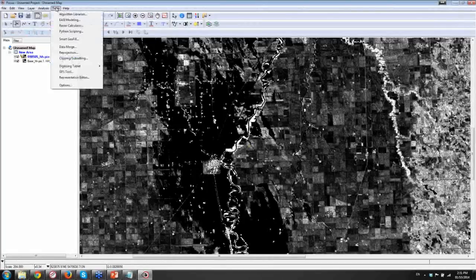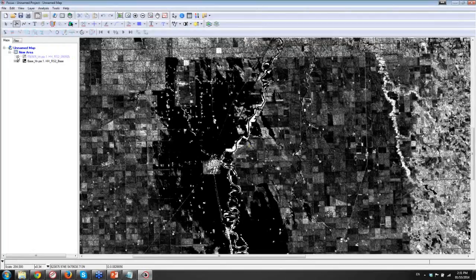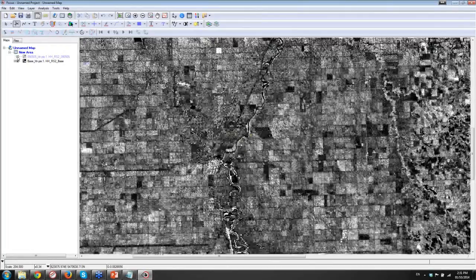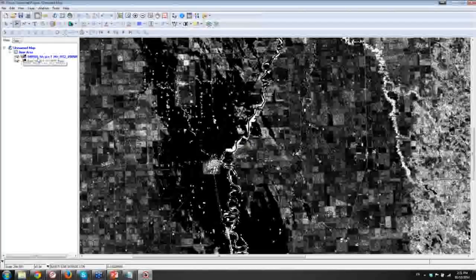So in order to derive the changes correctly, what we need to do is, first and foremost, align our imagery. Now these two images have already been co-registered. In some cases, we can't always get the same resolution or the same viewing geometry over the same location, maybe because when it's a disaster type situation, we tend to go with the first image that's available in order to get an answer quickly to people who need to derive information.